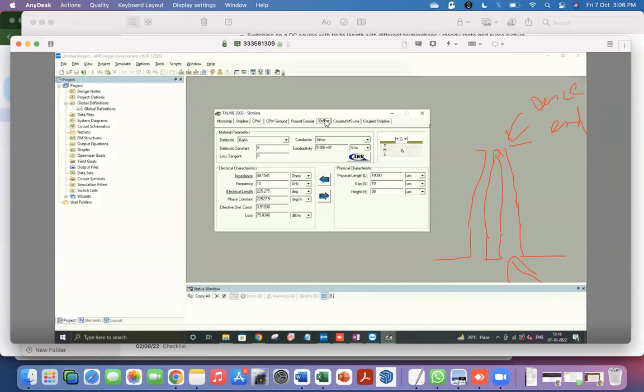And this is what is called a slot line transmission line. Okay, so if you see the picture here, let me draw it again. So it's just basically a very large metal plane on either side with just a gap in the middle. In some sense, the closest is to think of just 2 wires next to each other, but it's a little bit different, because the ground planes here are considered to be, at least in the idealized model, infinite in dimension. So it's very big and the slot is very small. And then the field lines are basically inside this kind of a medium.